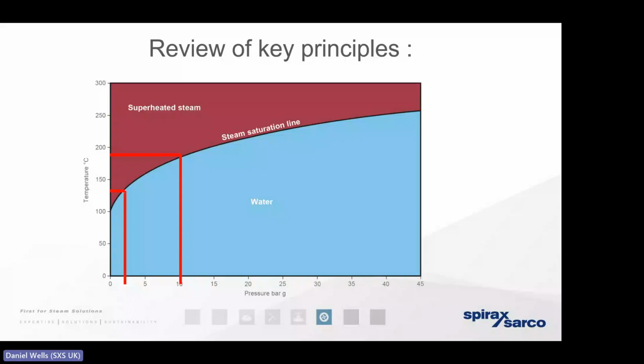So if that steam trap fails in the open position, just as the steam falls in pressure and expands, the condensate too may be falling from pressure at 10 bar gauge to 0 bar atmospheric. So this curve really demonstrates that when that happens, the condensate's got to fall in temperature too, from 184 to 100 degrees. The only way the condensate can do that is by giving up a lot of energy. So that means that a certain mass or a certain percentage of the condensate is got to boil off.